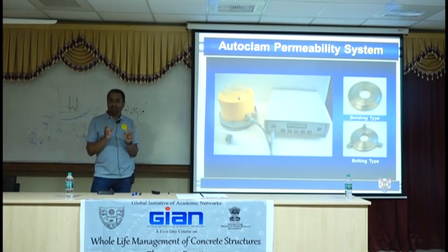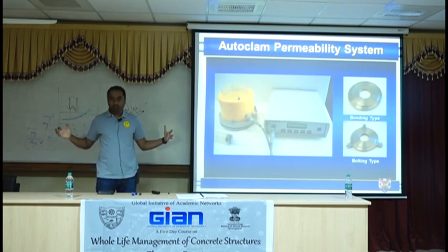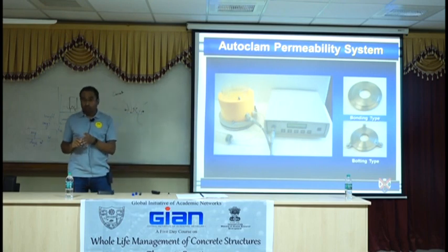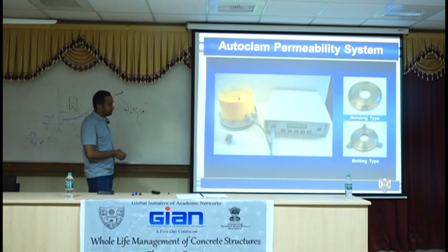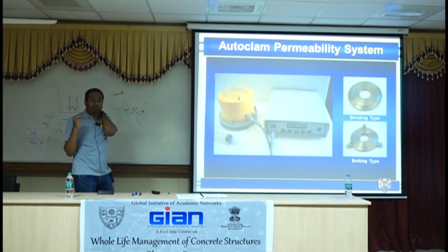Air permeability is the same scale. It has to be dry concrete. So what we do is we test the air permeability first. We let the air pressure dissipate. We let it open. And then we do the absorption test. Then we do the water permeability test. Okay? The manual tells you how exactly to do it. So any test that you buy, if it has more than one capability, read very carefully how to do the sequences.